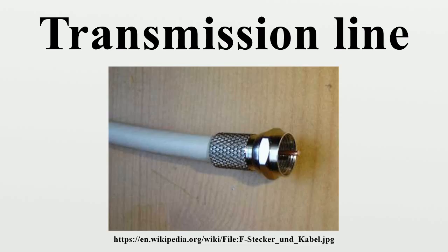The disadvantage is that star quad, in combining two conductors, typically has double the capacitance of similar two-conductor twisted and shielded audio cable. High capacitance causes increasing distortion and greater loss of high frequencies as distance increases.